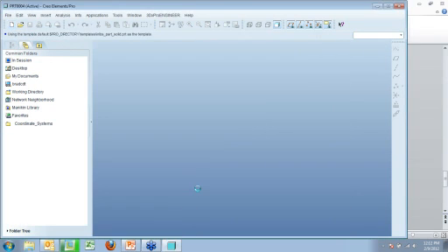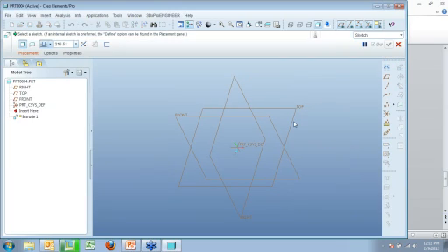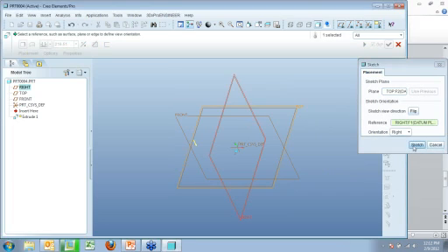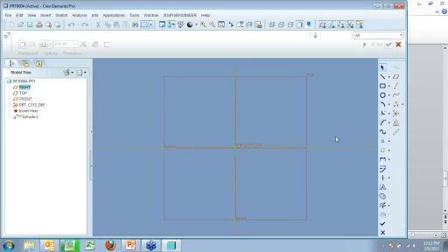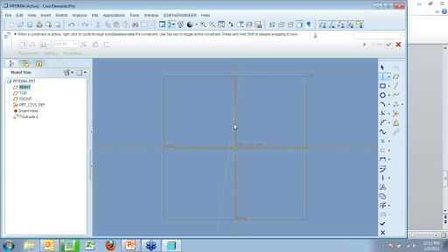So I'm just going to create a simple part. If you guys want to count along the mouse clicks, you can. I counted earlier, it was about 38 or so. Right click, define internal sketch, select my plane, click sketch. I want to create some construction center lines to make this square.